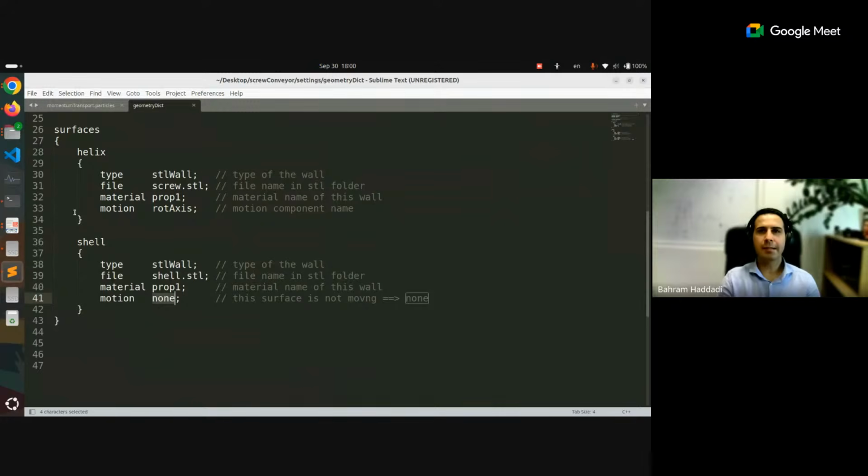So basically, as a general recommendation, as always, you have to go for a compromise between accuracy and speed. Of course, you want it to be as accurate as possible, but on the other hand, you have to have an eye on the speed so that you can do a simulation in reasonable time. As Hamid mentioned, make it as detailed as possible, but not too detailed. If there are small gaps or small details that do not really change the phenomena that you study, just simply forget them and move forward.